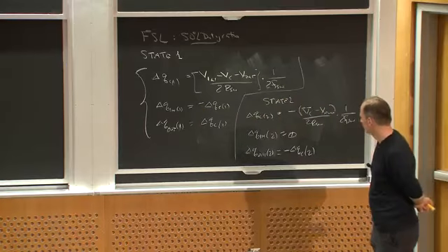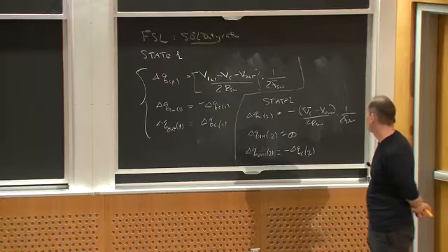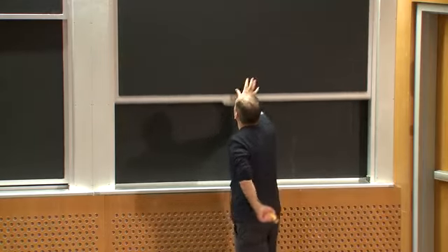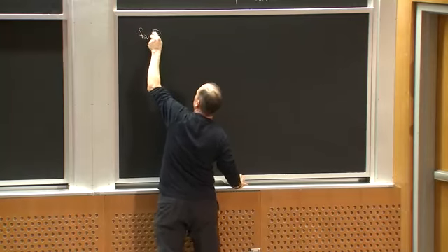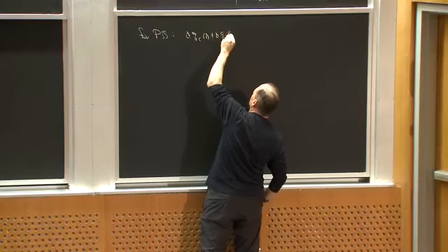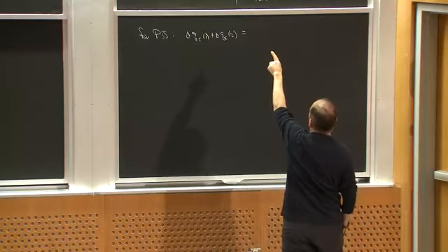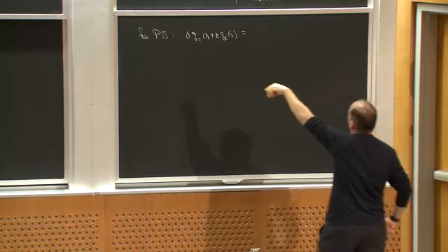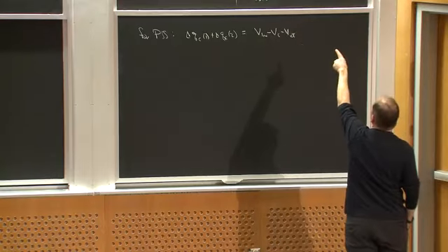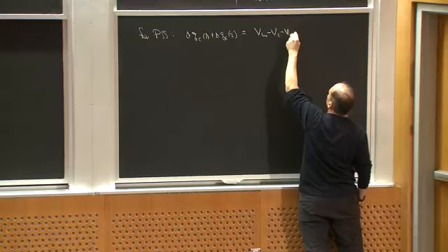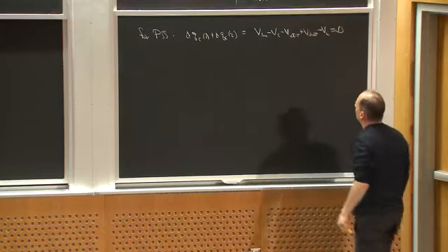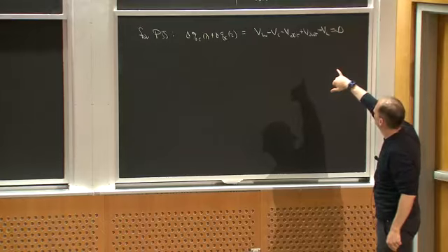What constraint do I get off of this? Well, what I need is delta QC1 plus delta QC2 to add up to 0, right? That's a constraint for periodic steady state. So for PSS, delta QC1 plus delta QC2 is equal to 0, which gives me, I can ignore the 1 over 4 F switch R switch, Vin minus VC minus Vout plus Vout minus VC plus Vout minus VC is equal to 0, okay? And what this gives me is that VC is going to be half Vin.